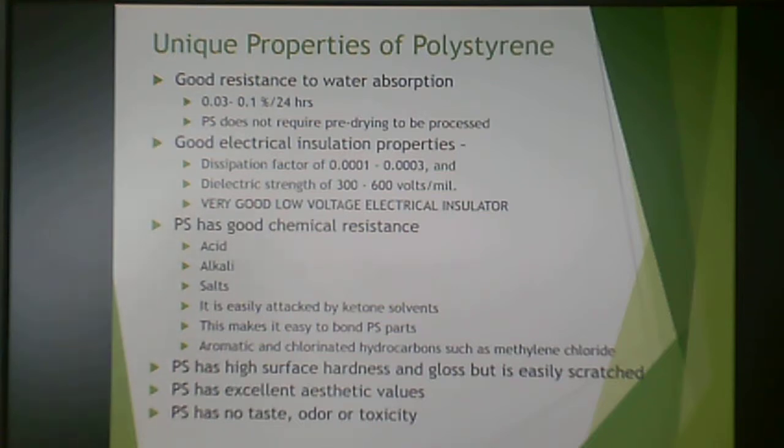This has good resistance to water absorption and does not require pre-drying prior to processing. Good electrical insulation properties. It is a very good low voltage insulator. It has good chemical resistance to acid, alkali, and salts, but it is easily attacked by ketone solvents. It is easy to bond polystyrene parts, and you can use aromatic and chlorinated hydrocarbons like methylene chloride to do